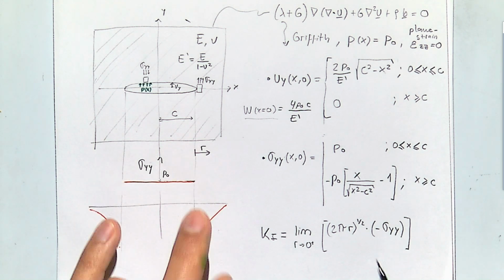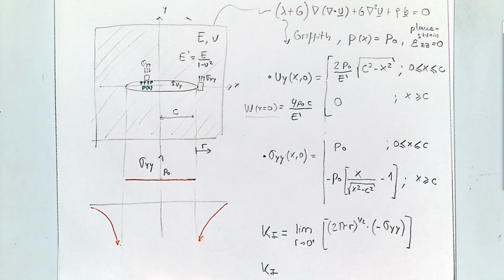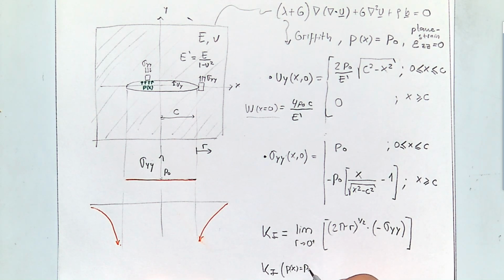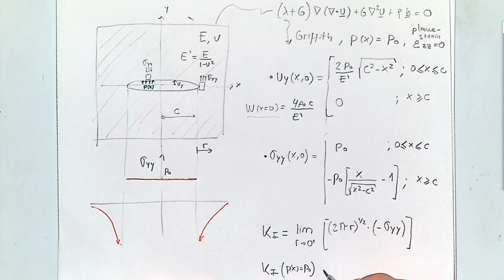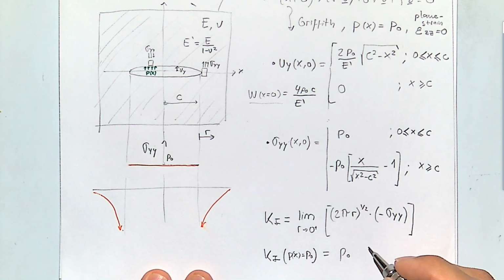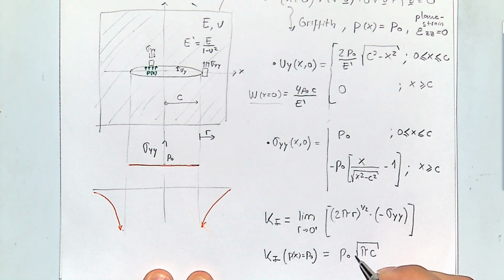So somehow, when you do the math, it's not that you multiply 0 times infinity, and at the end, it's not actually exactly like that. But when you take the limit, this tends to a finite amount. And for example, the stress intensity factor for a constant pressure for an open mode fracture is equal to this: the net pressure times pi fracture half length square root.